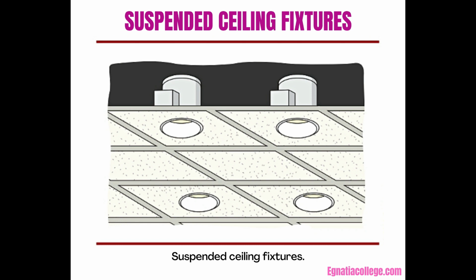The fixtures installed in this ceiling are a lay-in fixture, suitable for recessed installation. In most residential applications, these fixtures would still be classified as recessed. And the CEC requirement of a minimum of 13 mm clearance from structural members must be maintained, Rule 30-902. This figure shows the typical layout of the suspended ceiling with the recessed light fixtures mounted.